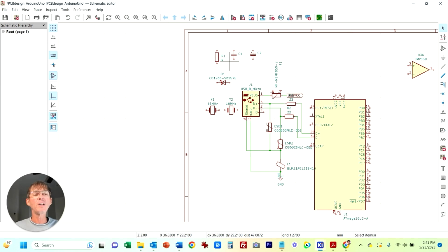These are just tiny little surface mount capacitors, usually nanofarads, potentially picofarads, up to usually a few microfarads. And then for the main power coming in, the high power, high voltage, we'll use a different type. We'll use an electrolytic capacitor, which does have polarity.